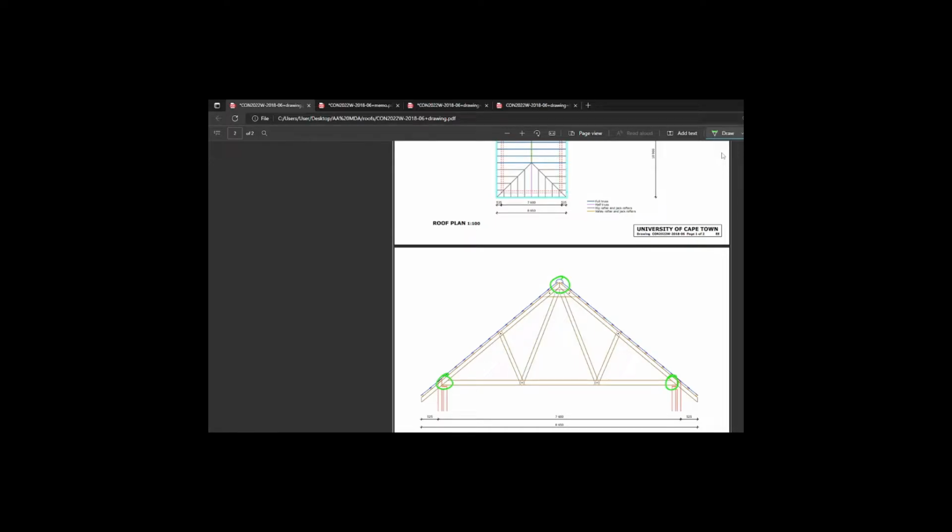Okay, so you can see clearly that in the absence of any connectors, we have to assume they're fixed somehow. And in the diagram, if there's a dot, dot would be bolt. No dot is, we'll call nail plate. In the absence of any visual indication, we have to assume that there's a nail plate there. Something has to be holding those pieces together, and it's a nail plate. I would argue that this one's not so obvious because we already have a collar there. So to put a nail plate here, yeah, anyway, it's extra. Let's call it extra.